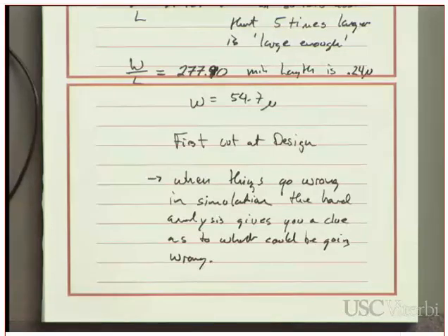So if they tell you that their output impedance depends on the transconductance and the channel length, as well as, say, the gate-source and gate-to-drain capacitances, then you know where to look if you're finding a bad match with the output. You have a question? No?